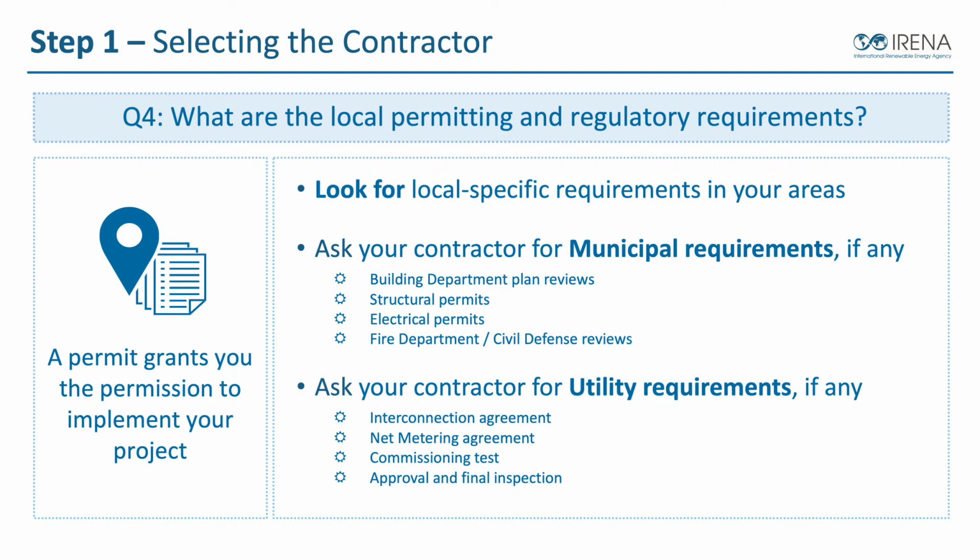We also want to look at net metering agreements. Net metering means if I'm connected to the utility system, then if I export energy back into the electrical grid, how do I get credited? And what's the program for import and export and energy costs when I send power back into the grid? Things like that. So that could be a net metering agreement.